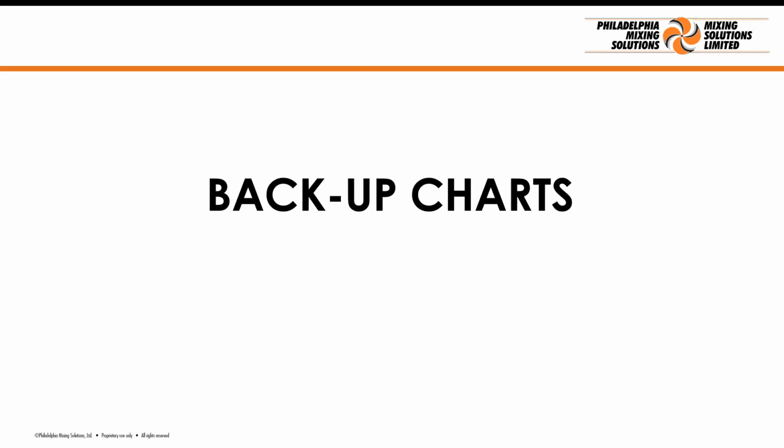On 5 topics in a mixing course, the first thing I think is the fundamentals of impeller characteristics, and how we quantify the flow, the shear, the power, the efficiency. The second thing would be simple liquid phase blending. If I'm doing pH control with a waste stream and adding an acid or a base, how long do I need to mix to ensure that the contents of the vessel are well mixed?